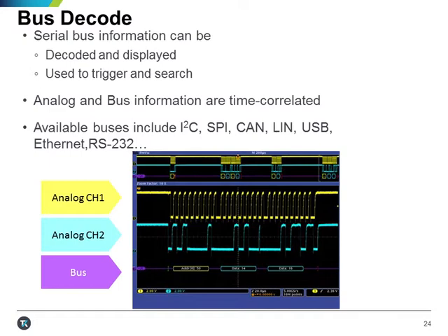Some buses, especially really common intermodule buses like RS-232 and USB 2.0, can be decoded by relatively cheap bus sniffers. The difference between the scope approach and the standalone bus decoders is that the oscilloscope approach allows you to look at any related signals on a time-correlated display, which allows you to see how many bus commands sync up with other events in your system.